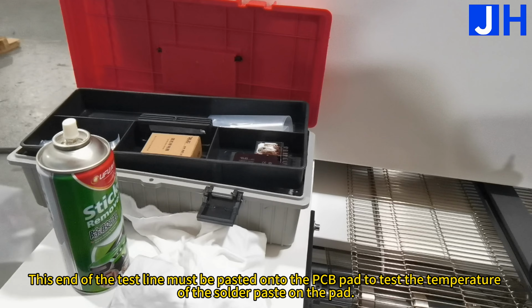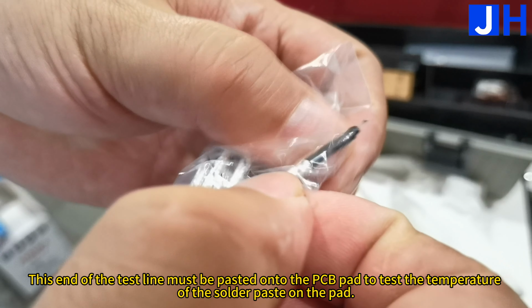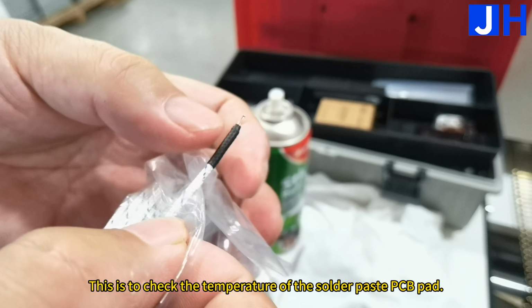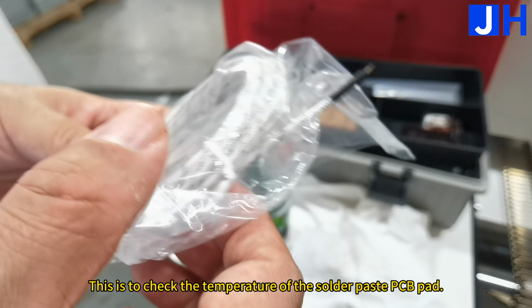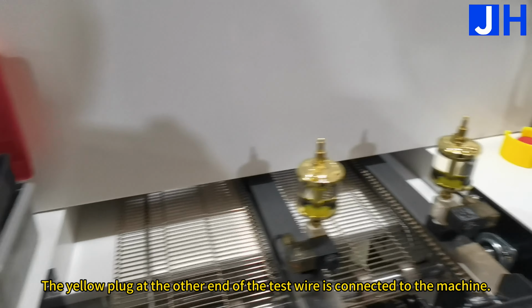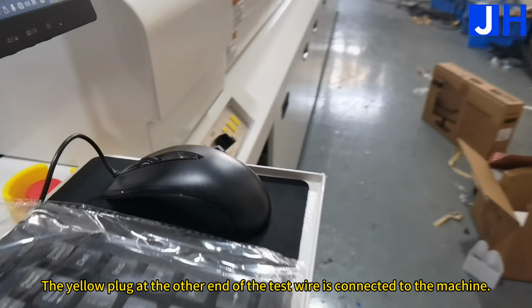This end of the test line must be pasted onto the PCB pad to test the temperature of the solder paste on the pad. This is to check the temperature of the solder paste on the PCB pad. The yellow plug at the other end of the test wire is connected to the machine.